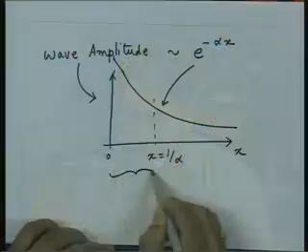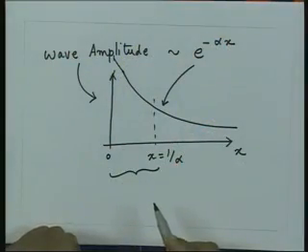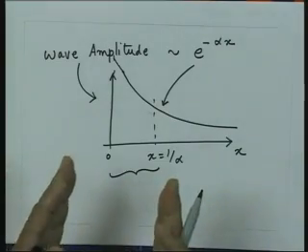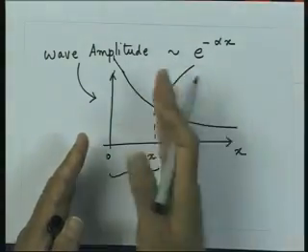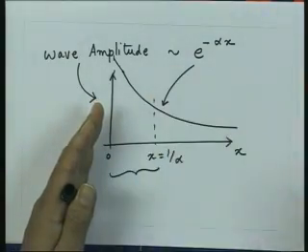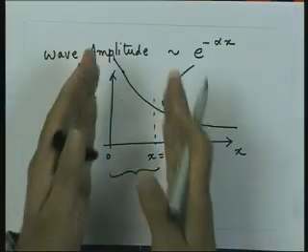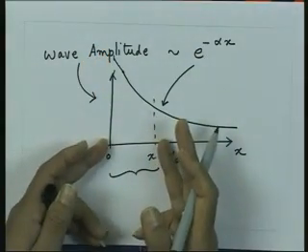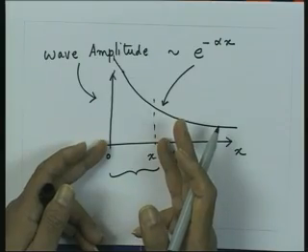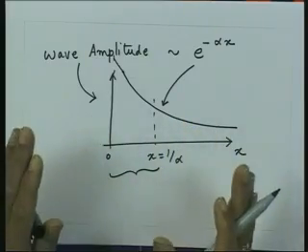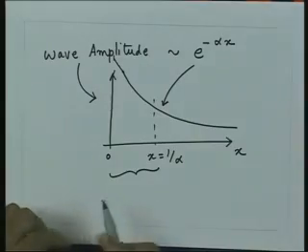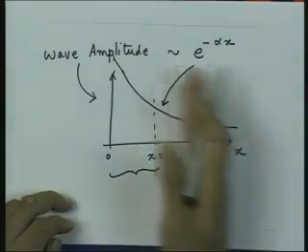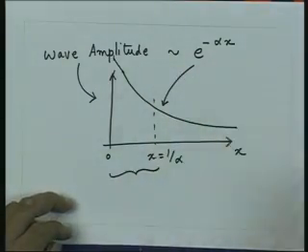So, if I say this is the effective width over which the wave propagates, I can now say that beyond this the medium does not exist, because there are no fields beyond this point. So, no matter what is the thickness or the depth of this conductor, only this thickness where the field died down to 1 over e of its initial value matters in the propagation of the electromagnetic wave. Beyond that, whatever conducting medium is there, it does not really affect it.